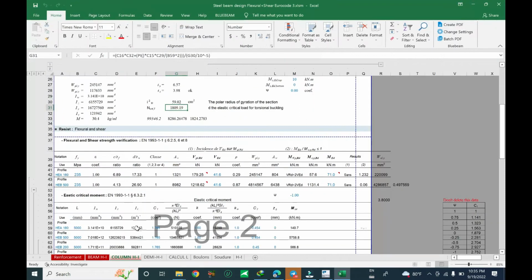When you include the distance, in the Eurocode it is ZG. So the section will reduce its capacity when you consider it from the shear center to the applied load at the top plane. You see here the result of the final MBRD for the lateral torsional buckling is now reduced to 39.7. Yes. Now let me come back. In the class 10, there is no option to change the condition, stabilizing or destabilizing. Let me click OK again. This is my assumption: I think the class 10 is not designed for the destabilizing load. It is designed for stabilizing load, not including the distance from the shear center to the load position.